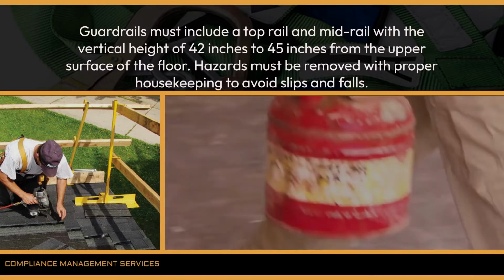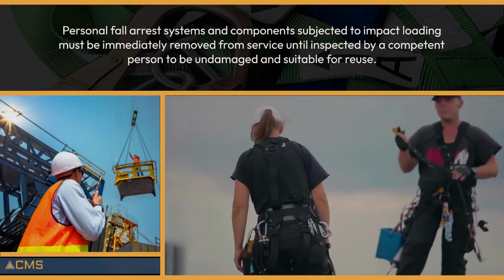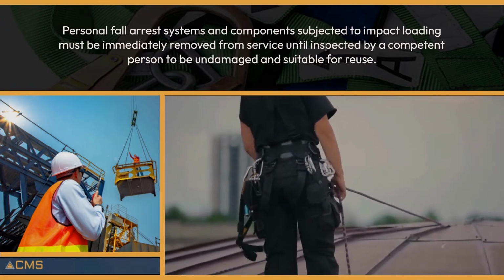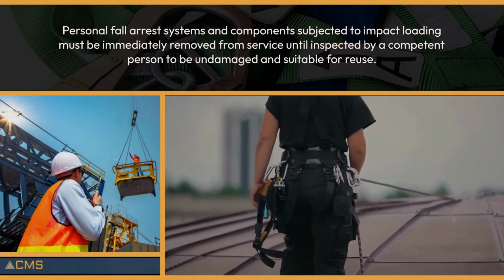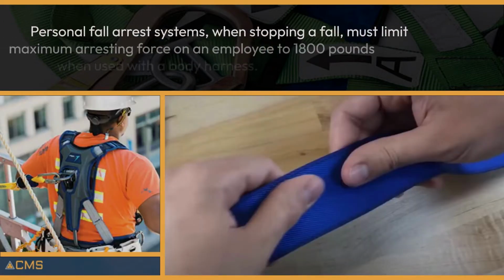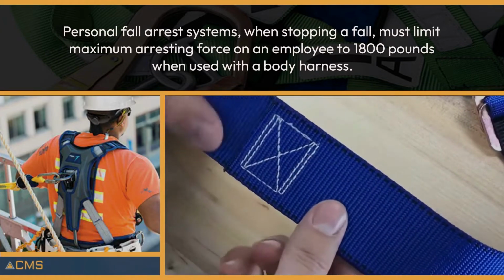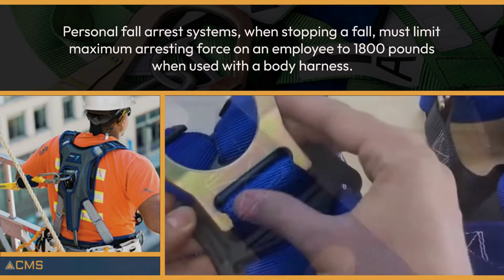Personal fall arrest systems and components subjected to impact loading must be immediately removed from service until inspected by a competent person to be undamaged and suitable for reuse. Personal fall arrest systems, when stopping a fall, must limit maximum arresting force on an employee to 1,800 pounds when used with a body harness.